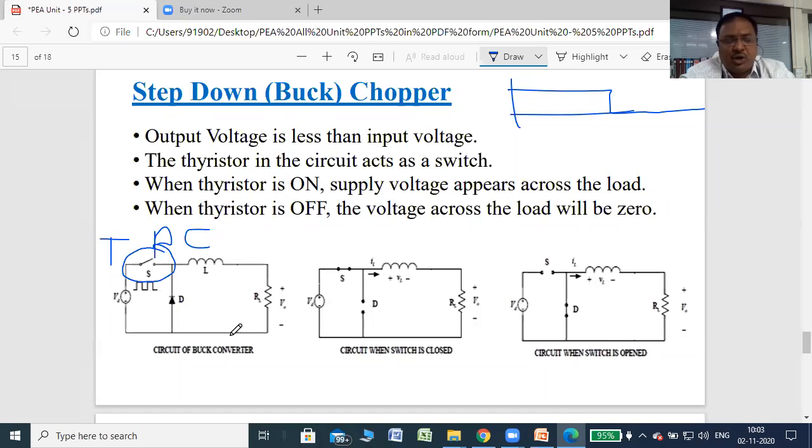All three circuits are not shown in the figure for simplicity, but we have to consider that without the triggering circuit, your SCR never conducts. If you are using a power device for high power, you require a protection circuit. So it is always there with the power device, but not shown in a figure. And if you are using an SCR in DC circuits, then you require a commutation circuit. That is also not shown in the figure, but it is always there.